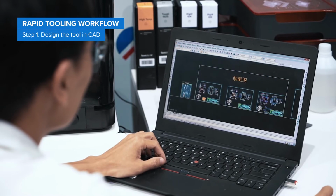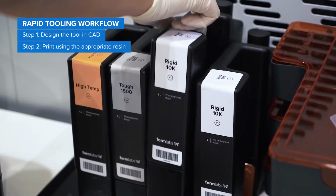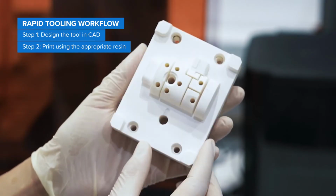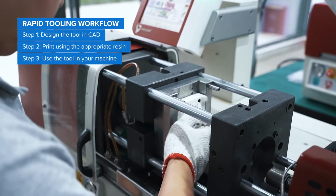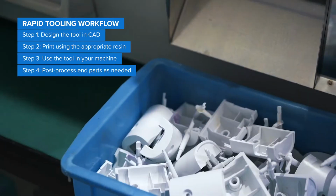First, design the tool in CAD. Then, choose the right resin from our expansive materials library and 3D print the part on a Formlabs SLA 3D printer. Next, insert the 3D printed rapid tool in your machine and use it in your normal workflow. Finally, post-process the end part as needed.